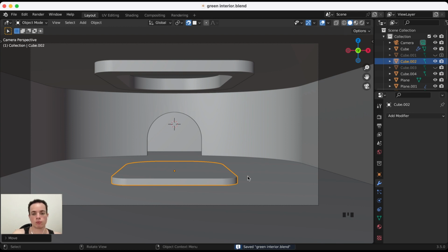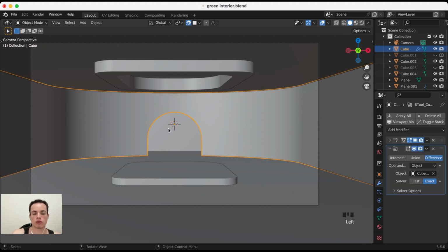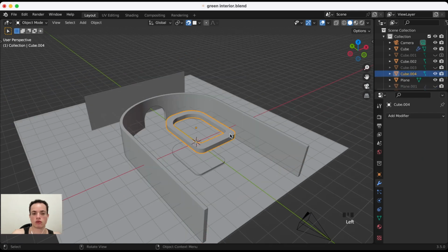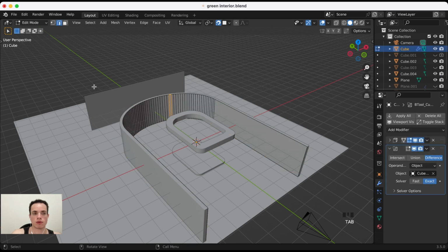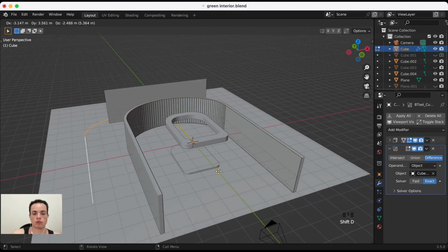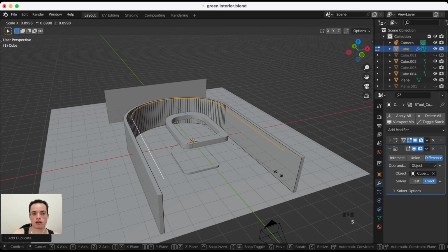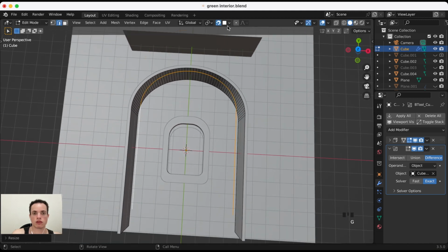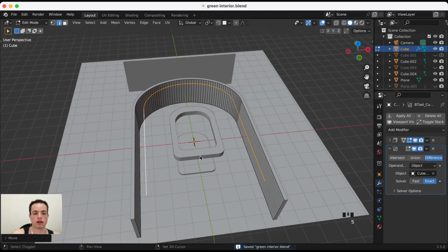Now we need to put the columns on the side, so we can get this, and we want the column to follow this shape, so we can get this, we can hide, H, also this we can leave, get this, tab, edge select, alt, get this, shift D to duplicate, escape, and then we can do a little S if you want, and move it, we don't want the snap, move it like this, and turn this into a curve.